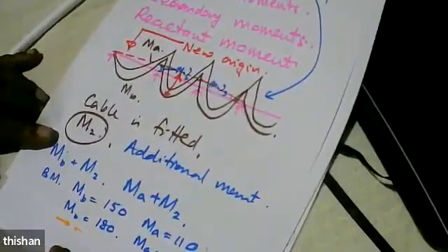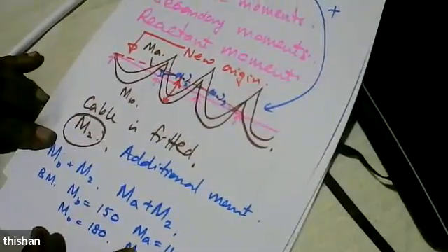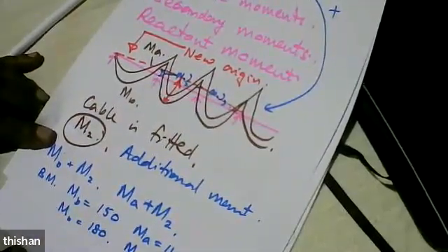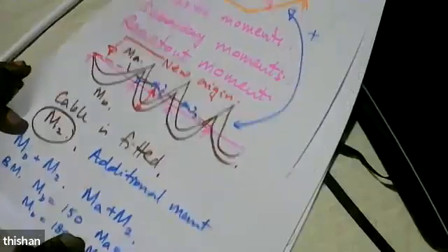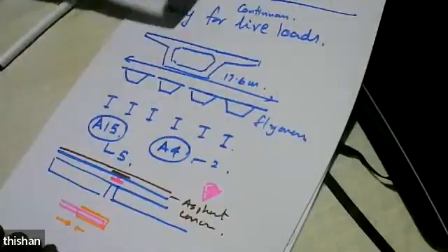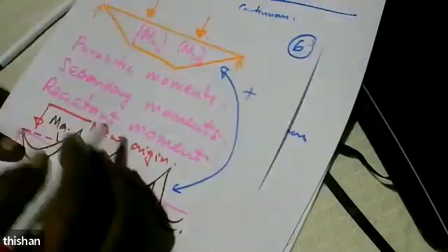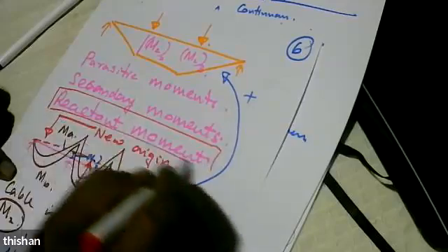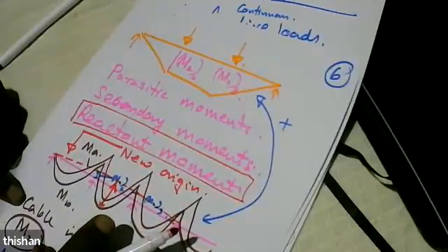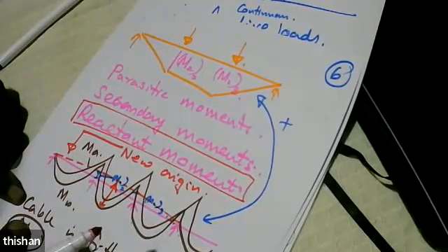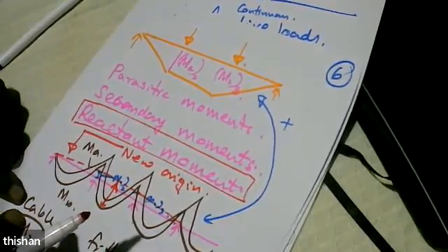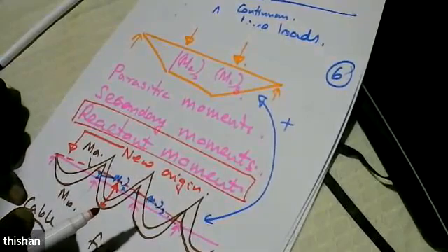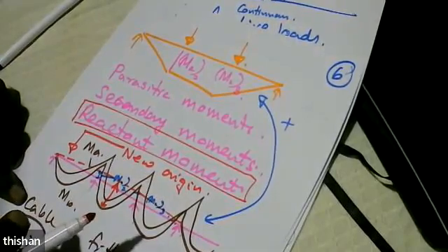the bending moments are going to be like this, where the bending moments in a span section will increase. Bending moments over the support section will decrease. Now we call this moment parasitic moment, secondary moment, reactant moment, and most people use this term because parasitic means bad. But I'm going to show you it's not bad, it's good. Second means small, right? But I'm going to show you it's not small either.